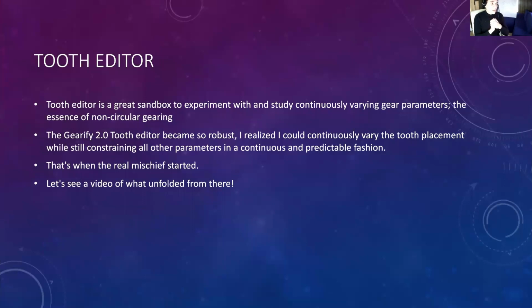So in the end, this tooth editor, which observes all of these constraints, became an extremely powerful sandbox environment to experiment with and continuously vary all the parameters of the non-circular gears and their involute teeth. In fact, I suddenly realized that it had been so well parameterized that I could actually continuously vary the placement of the involute teeth along the pitch curve.